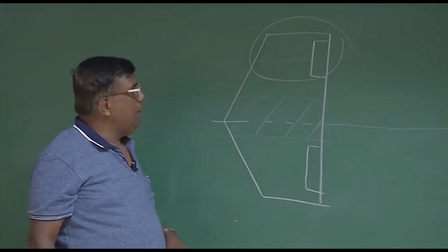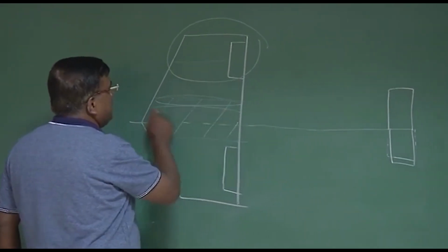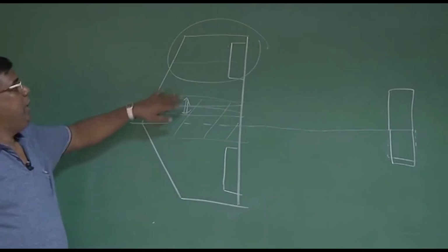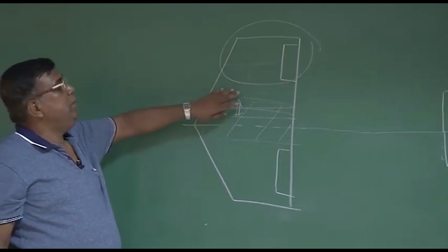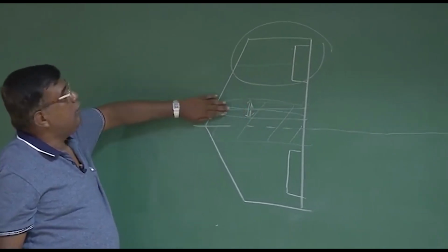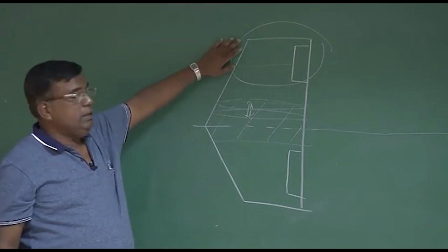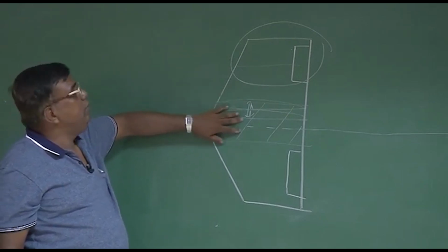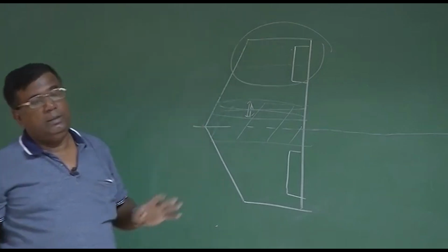Now we can recover. Another way is you select an aerofoil such that it has a smaller stall angle compared to the aerofoil here. That is, one of the ways it could be handled is by adjusting the t by c of the aerofoil. Let's say this aerofoil will stall at 12 degrees, and this aerofoil will stall at around 13 degrees. So even if there is a stall situation, this portion will stall, and this will give a warning to the pilot, and he can control the airplane through aileron. So this is also possible.